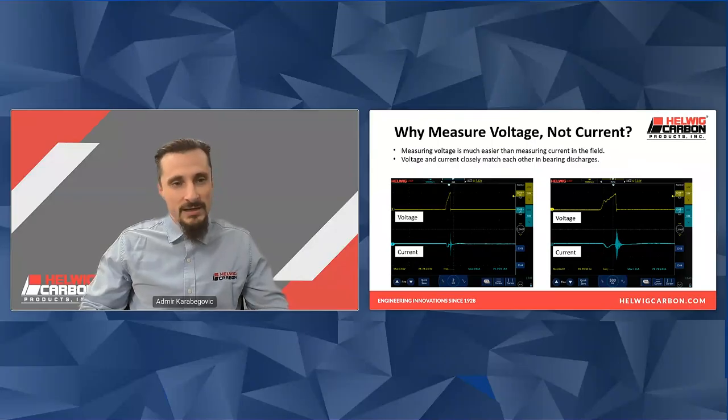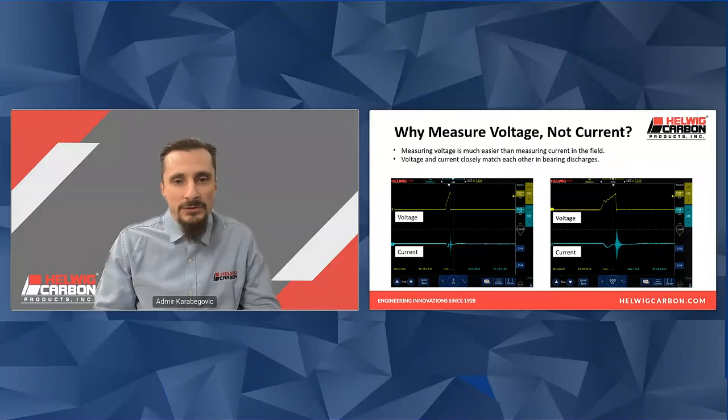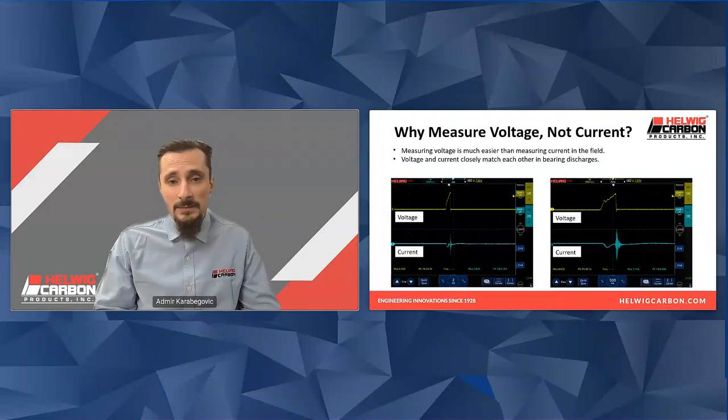So many customers ask, why measure voltage and not current? Measuring voltage is just much easier than measuring current out in the field, especially. You could measure current with a Rogowski coil, but again, it's difficult to use in a perfect test lab setting. It would be preferred, obviously, but once you're in the field, it makes it a little more difficult.